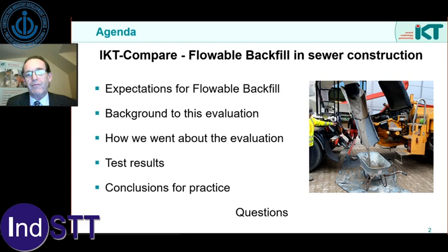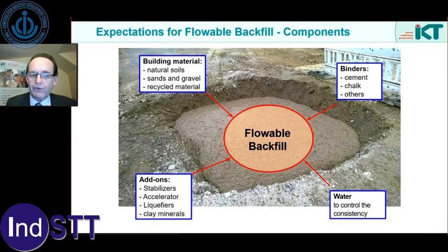But it is a mixture of materials. Natural soils or sands and gravels are brought in, or recycled materials can be used. You have binders, you have various add-ins like stabilizers, and its consistency is usually controlled by the amount of water that it contains. But what are its advantages?